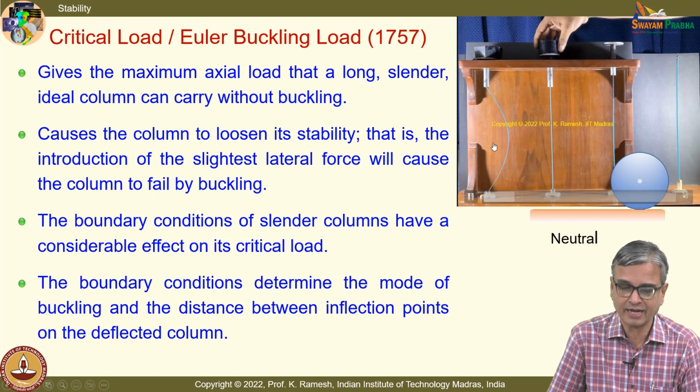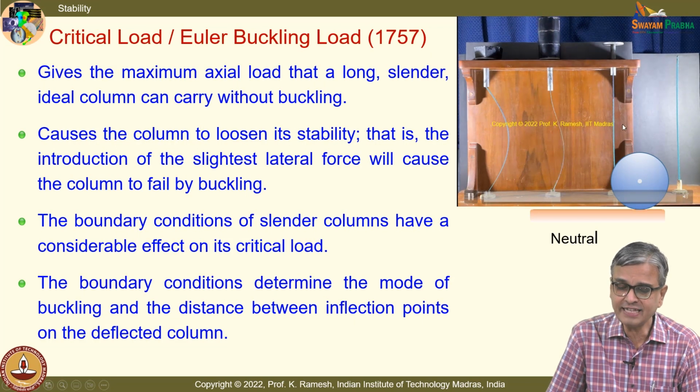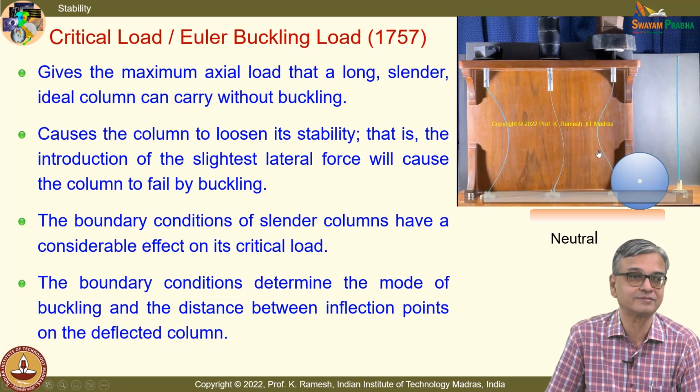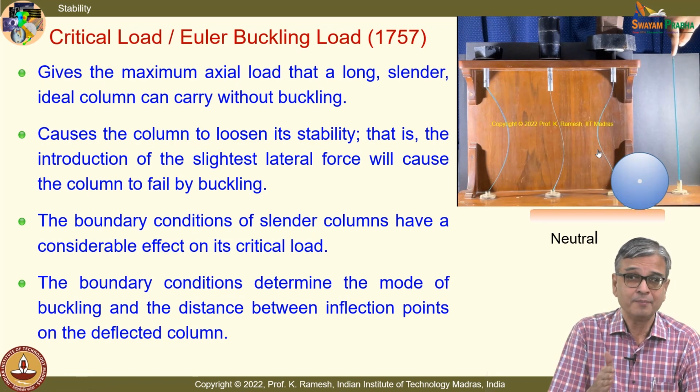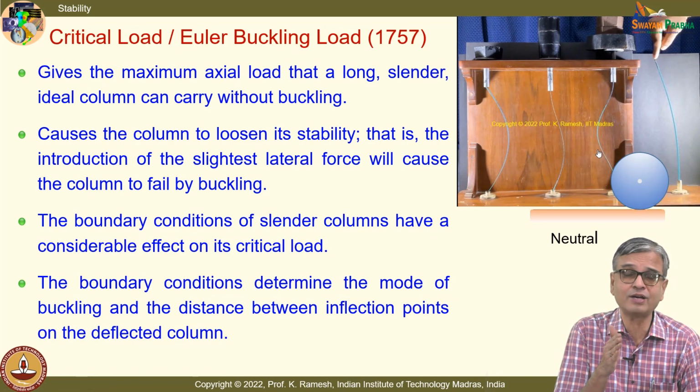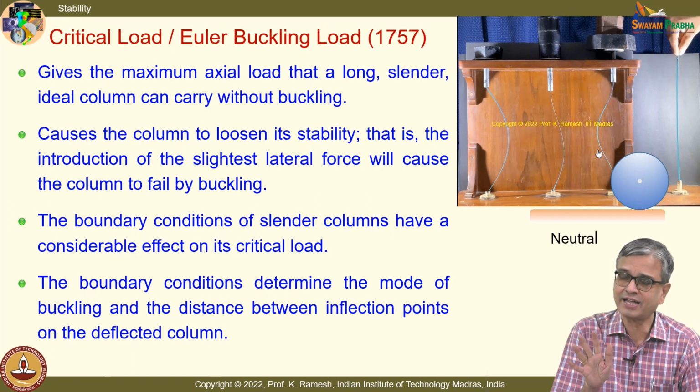This load is higher than this. Here you can see in a subtle fashion, and you can see that in a definite fashion here. I have one equilibrium position, I apply load, I have another equilibrium position, I apply another load, I have another equilibrium position. So, these are all neutral equilibrium positions, but the transition from one to another is sudden. So, it loses its stability. Okay.